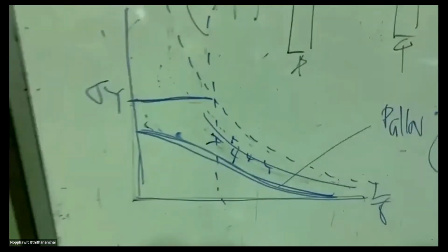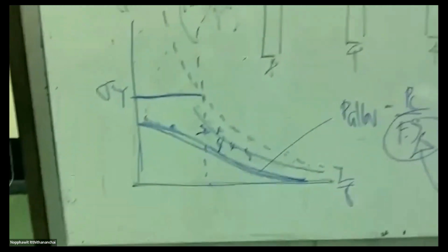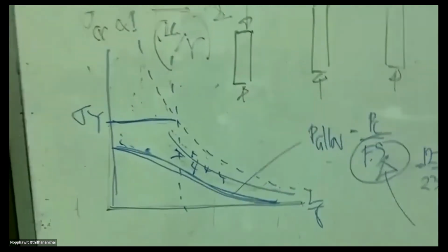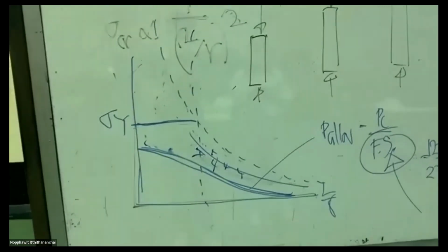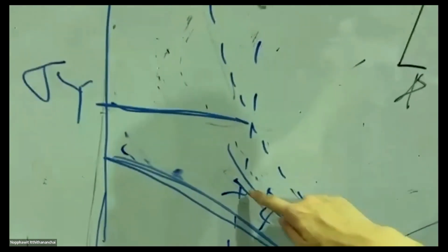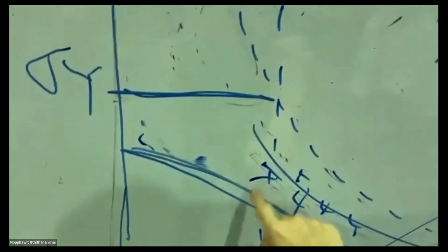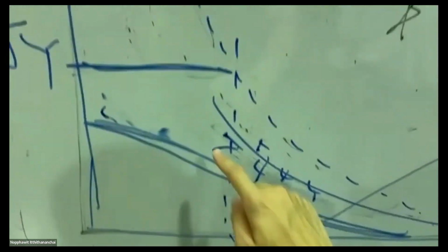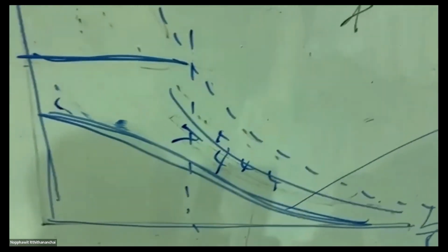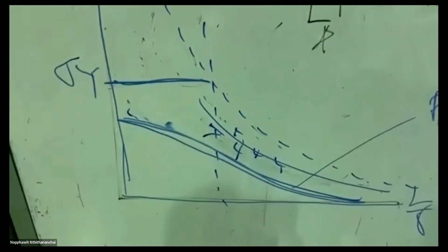And then you have to draw this graph like in our lab direction. Something like this. We have 4 specimens, so we have 4 points here, around here, no, here, because this part is the short column. What we test is the long column, so it will be here. Draw the curve like this. Ajahn Siddhichai told me that he already taught you this in the lecture class, right?